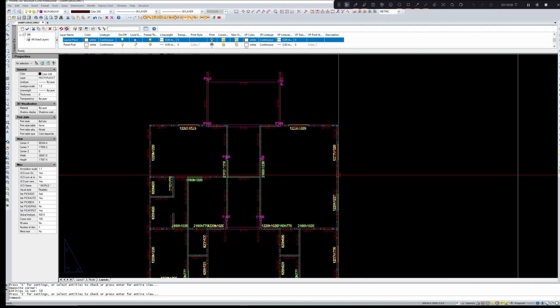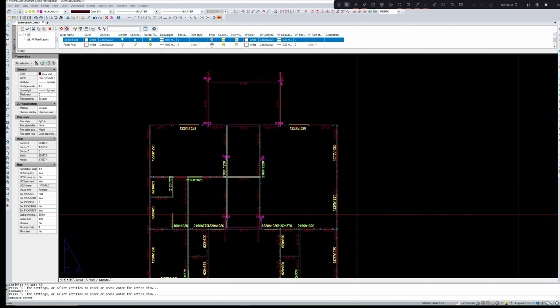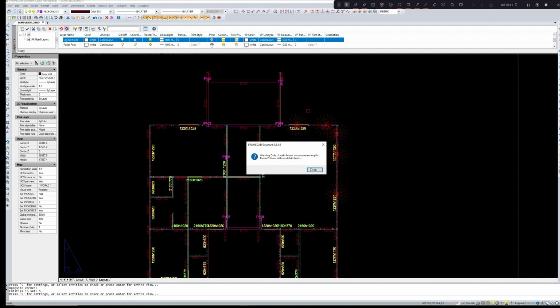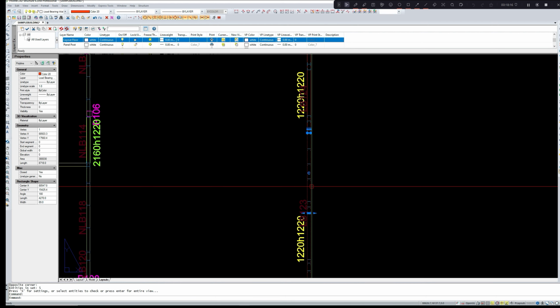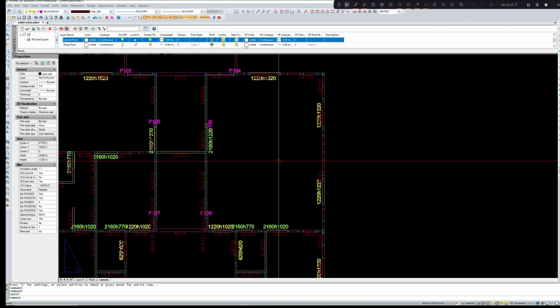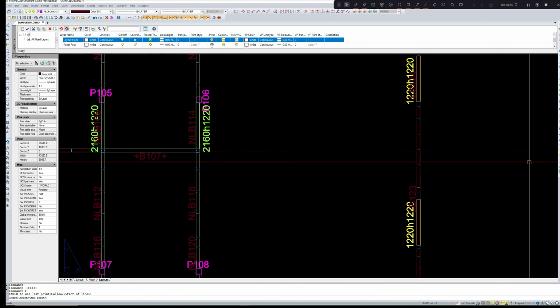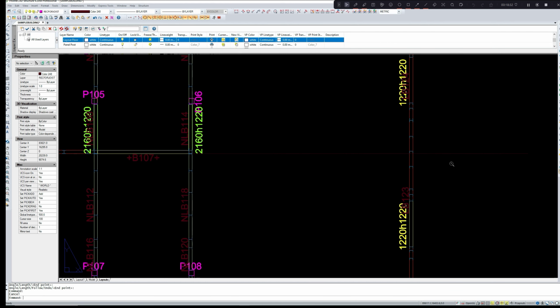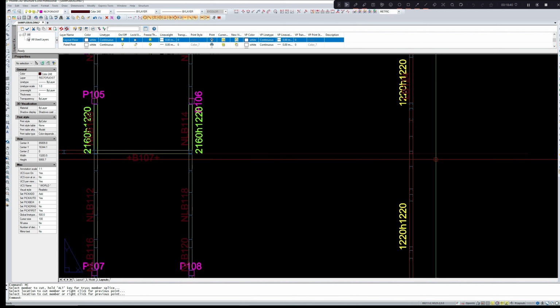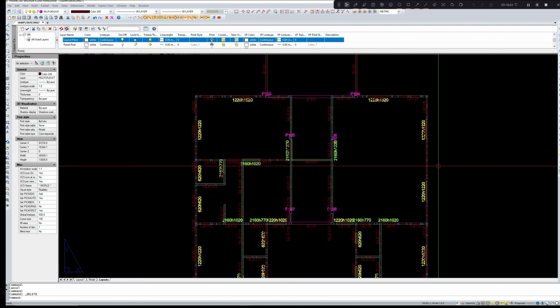So let us check part by part. IC. So this part has one wall which is long. This member seems to be very long. So let us cut this member at a point here. Line command. Now MC is the command for cutting the panel. Select the panel, cut it here. Okay, delete the line. Now let us make an IC command.